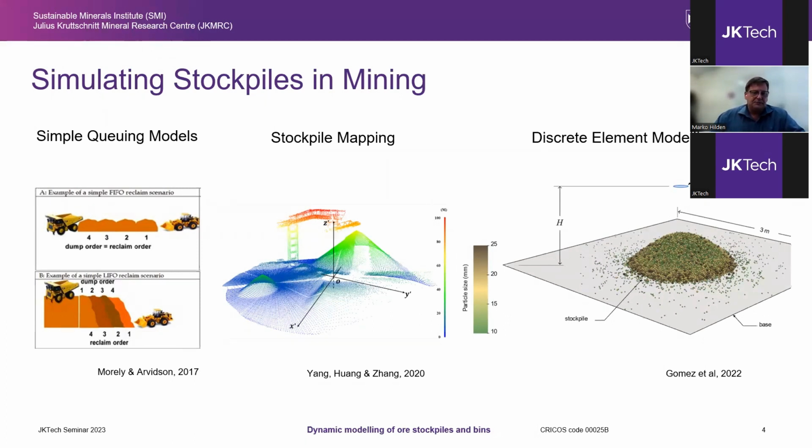With recent developments in drone LiDAR and photogrammetry, we now have powerful tools for stockpile mapping that give very accurate measurement of stockpile volumes, but these measure the surface profile and are not able to track the properties of what's inside the pile. Also, these measurements tend to be relatively infrequent, such as weekly.